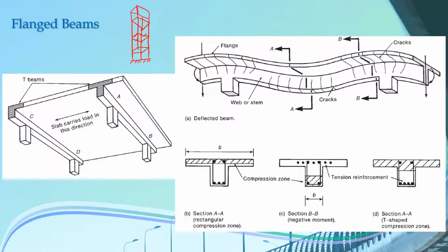However, if you look at real structures, then often the beams and the slab are cast monolithically. The reinforced concrete slabs that are used in floor systems, the roofs of our buildings and our deck systems are mostly cast monolithic from the bottom of the beam to the top of the slab. And as these beams and slab are cast monolithically, they act as a single element and act compositely. If you look at this diagram here,